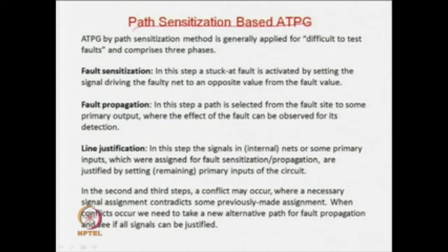So, now we will go for the approach which is widely used for test pattern generation, which is called path sensitization based ATPG, or which we are continuously calling path sensitize, propagate and justify. What do you mean by path sensitization? Already I told you that if there is a stuck fault, we have to drive it to the opposite value. This is just like there is an electric bulb with a fuse. You have to give power on, so that it goes to value 1, that is, it tries to glow.